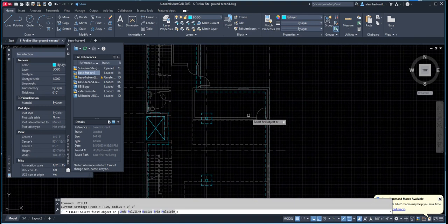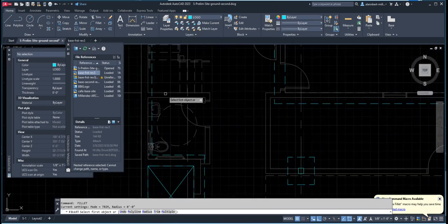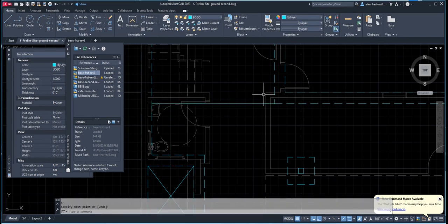If a wall does not carry any load, then it would not have a footing, and it may be this one. Or in some cases, the wall footing would extend. For example, if there is a lined up wall here, okay, the wall footing might extend and continue, even though sometimes there's no need to over there, but it just ties everything together.